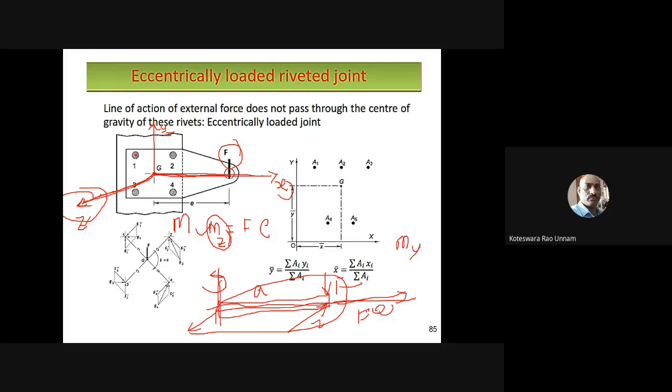If the moment is acting only about the x-axis, I will call it a twisting moment. Otherwise, if it is acting about the z-axis or y-axis, it is going to be a bending moment only. So why am I calling it a twisting moment? Because this axis coincides with the longitudinal axis. That means if the moment is created about its longitudinal axis, we will call it a twisting moment. Otherwise, we will call it a bending moment.